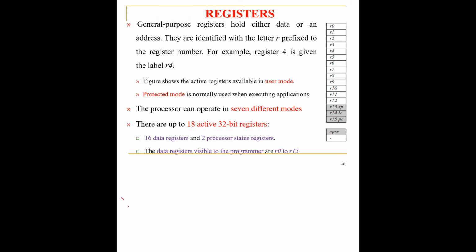If this is your ARM processor core, you will find registers here. You need to understand that the data that has come from the memory locations will be stored in these particular registers. This is your memory. The data manipulating instructions will be operating on the data in these registers. Please understand, data from these registers will not go to the processor. The processor will manipulate the data in these registers directly based on the data manipulating instructions.